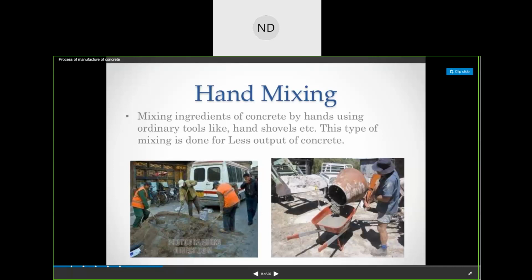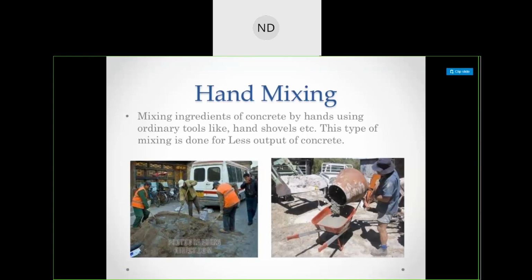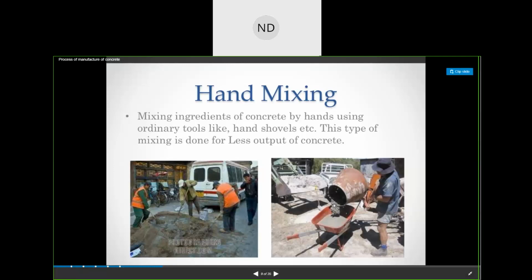So in the same way, when you hold something very closely together, that means when you have cohesion, you hold all the materials together, there is no air, obviously your concrete is going to be strong enough. So that's why we do compaction after pouring your concrete in your slab.